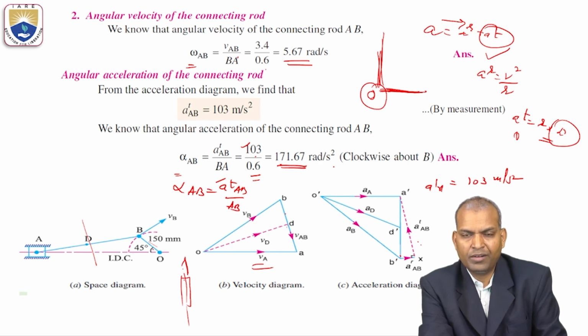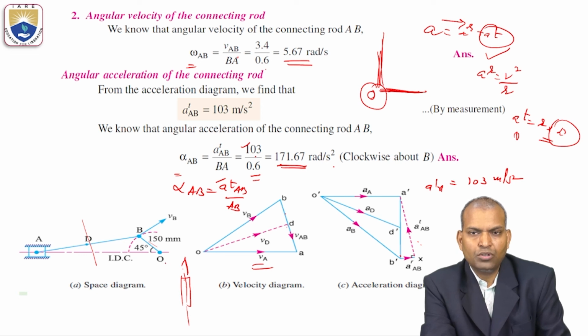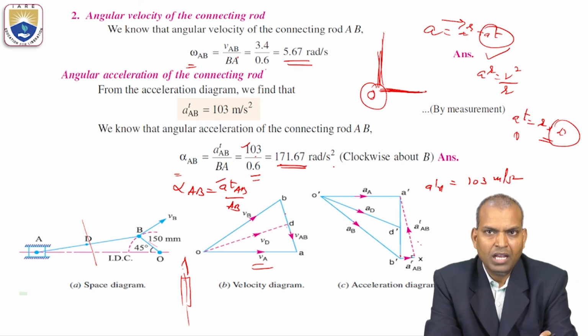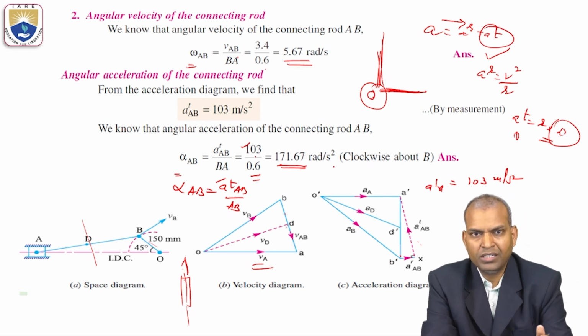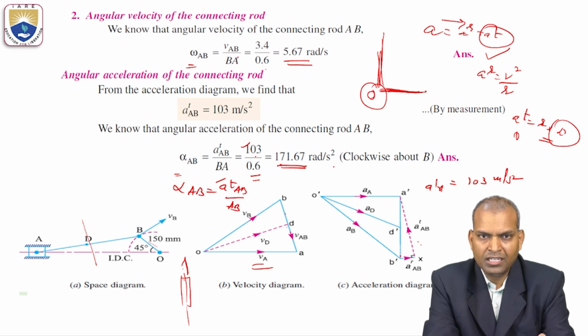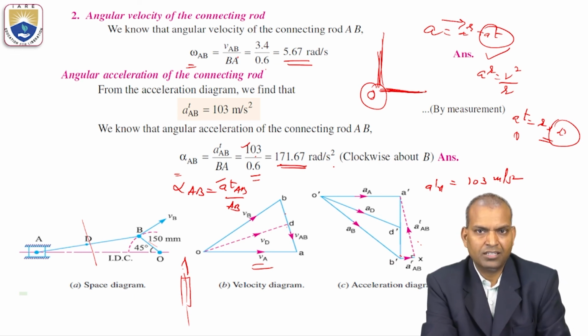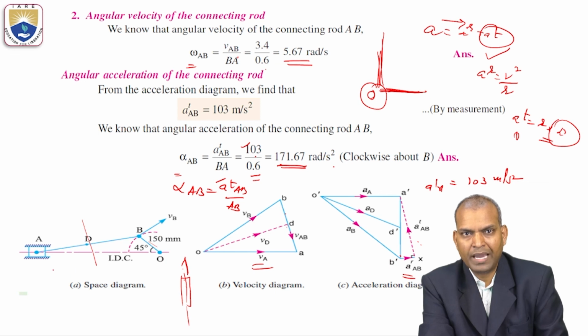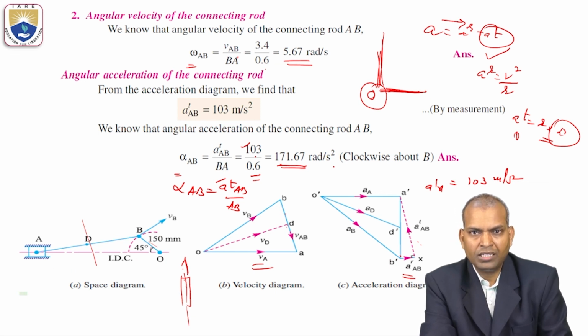Based on the requirement, the slider doesn't have radial acceleration because there is no rotation. What is its tangential component? So whatever known values are there, we have to calculate and keep them aside. Then, according to the data available, you draw the vectors in the acceleration diagram. Now the radial components AR are parallel to the links of the connecting rod. But for the slider, it is only tangential, meaning a parallel line. In the case of the other links, AR is parallel to link OB.